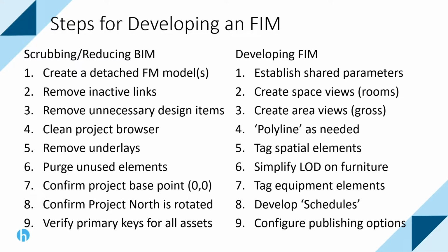Remember, Revit is a database and Archibus is a database, and if you want to ever compare the two, you can create views of the data that you can map to each other and look at and compare. So there's this nice feature in Revit for basically creating reports of your rooms and equipment and furniture and everything else. And then lastly, of course, you want to configure publishing so that what you push into Archibus or push into Autodesk Tandem product is exactly what you want to see in your operations system.